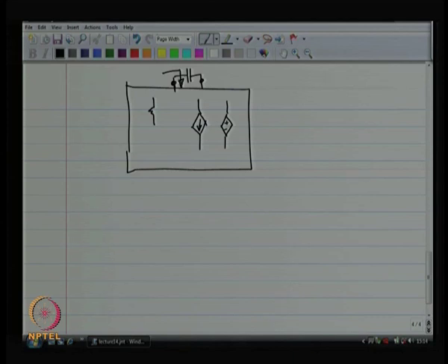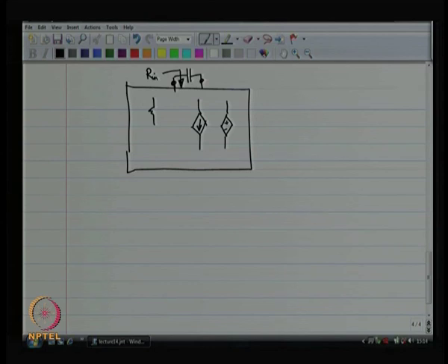Open circuit all the capacitors inside, open circuit the capacitor which you are holding outside, and you measure the resistance looking inside. There are no capacitors and presumably no inductors in this circuit, so you will only see a resistance, nothing capacitive or inductive. You measure that resistance for the capacitor that you removed, let us say it is C, and call it R in. So R in times C gives you a time constant.